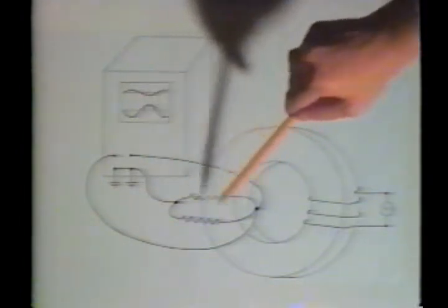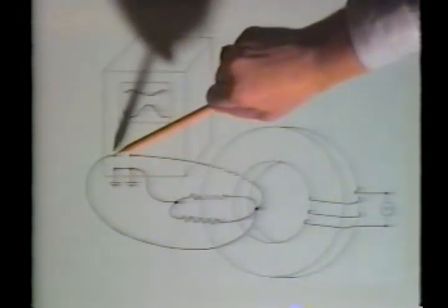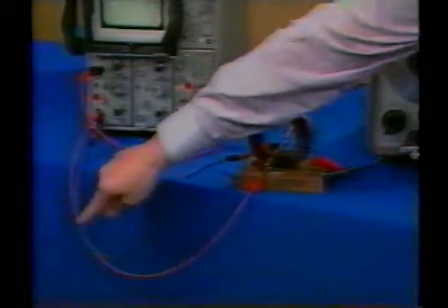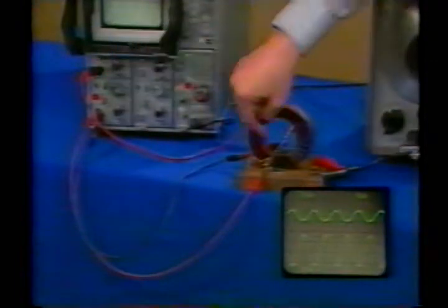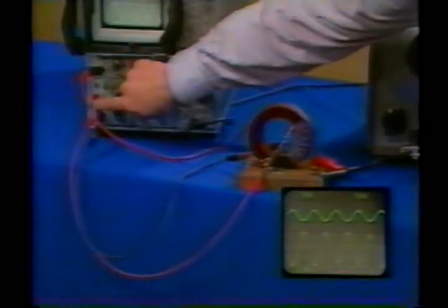The voltages observed with the leads connected to the same node not only differ in magnitude, but are 180 degrees out of phase. The ratio of the voltage magnitudes is 3. This is the ratio of the resistances. The probes are connected to the same node, and yet the voltages differ by a factor of 3 and are 180 degrees out of phase. We check to see that we don't have the traces on different scales by reversing the trace connections. Reversal of the leads results in a reversal of the traces.